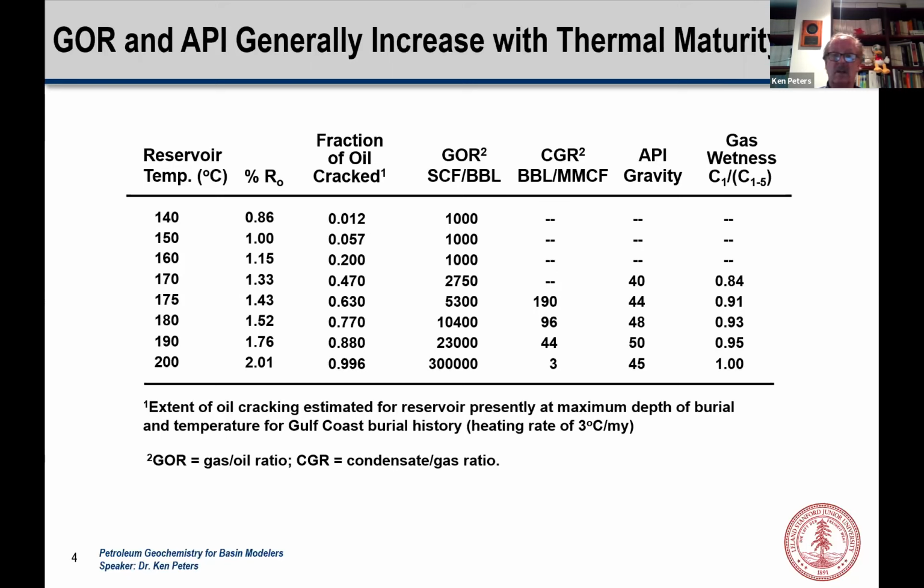Typically, gas to oil ratios are in standard cubic feet per barrel. For black oil, the GOR is less than about 2,000. Volatile oils are from 2,000 to say 3,000. And a gas oil ratio greater than 3,000 standard cubic feet per barrel, we would call those condensates. That's a very simple description, and there are some discrepancies in the literature about where those dividing lines occur, but they're descriptive, and as long as you define what you're saying, that's okay.